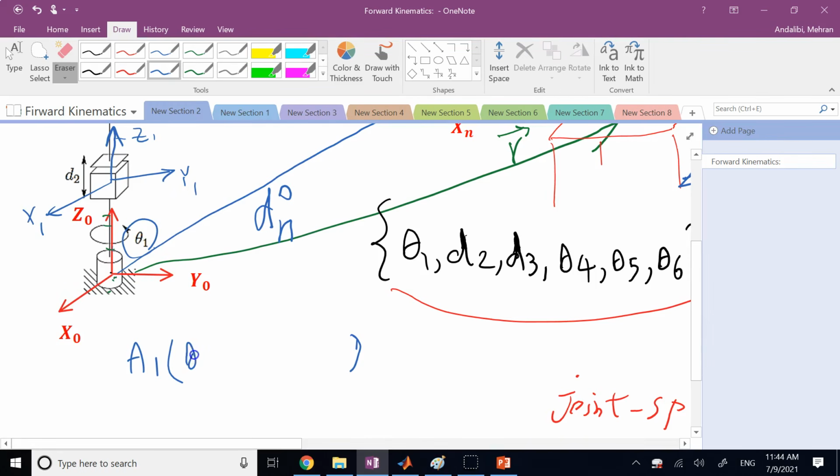So the only variable in them is theta 1. The twist, if there is any twist, which in this case there is not; the offset, which is basically this amount of offset from here to here; and if there is any link length here, a, which we use 0 really. Then if I want to write it in this case, it is going to be like that, and then L, and you have 0 and 0. So this is your d variable, this is your a variable, and this is your alpha variable.